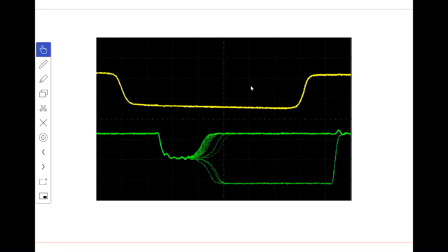They've actually done it in hardware with a bit of a feedback loop to adjust the timing until it becomes metastable. You can look in the book for details of everything else, but this green trace here corresponds to the output of a flip-flop. This would be a logic 1, this would be a logic 0. And you can see that the flip-flop really does get stuck halfway if the input changes too close to the rising edge. So this is not something theoretical, this really happens.